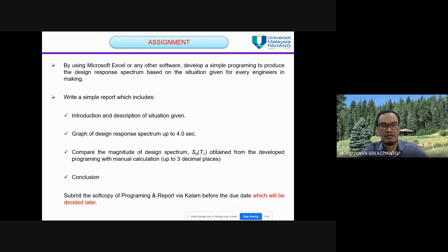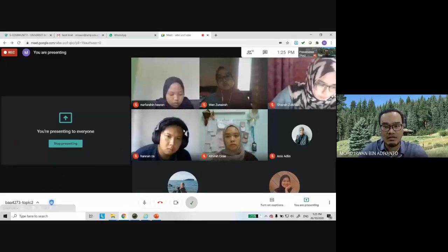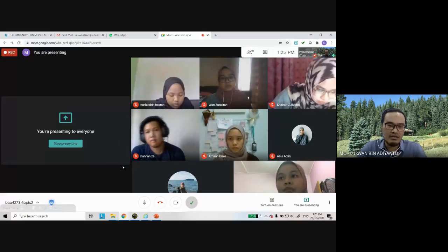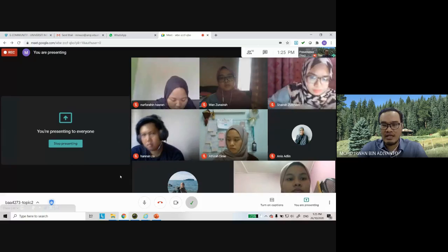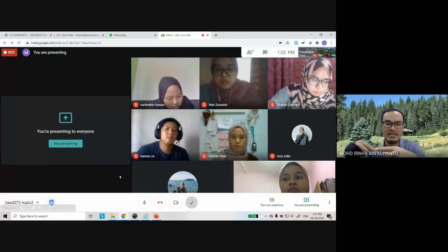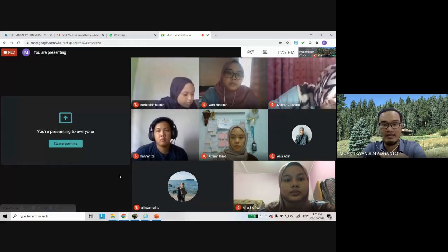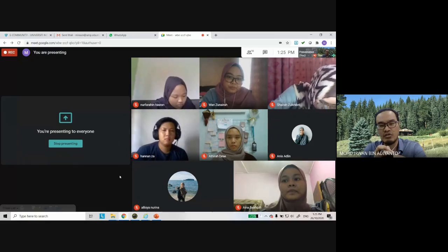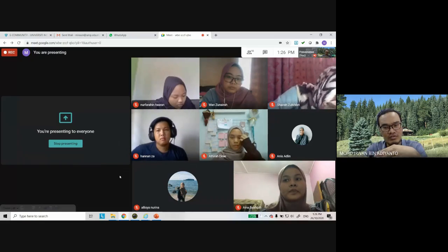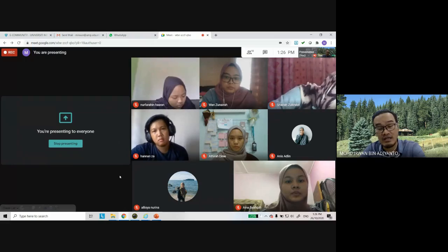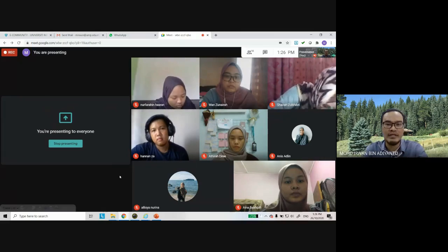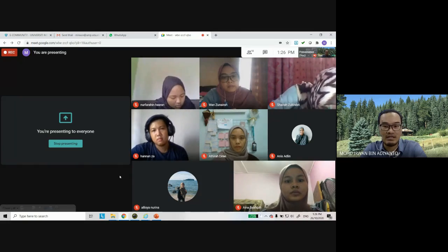Thank you so much for your attention, and I hope you can do more exercises. Maybe you can change the soil type, from soil type D to soil type A, or you can change the value of alpha GR from 0.12, reduce or increase it, and see what happens to the spectral accelerations.